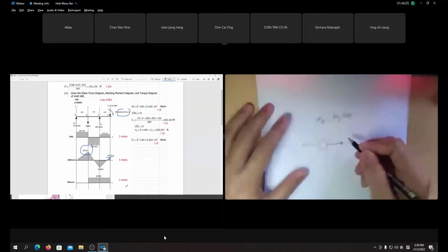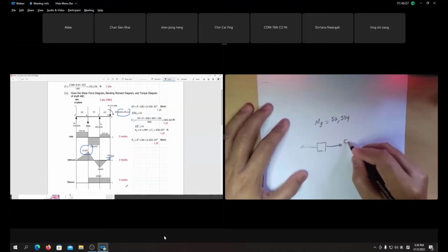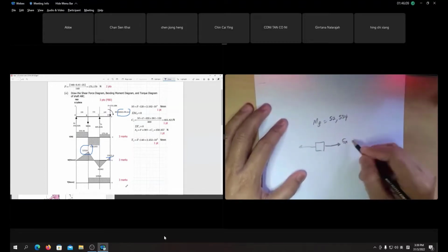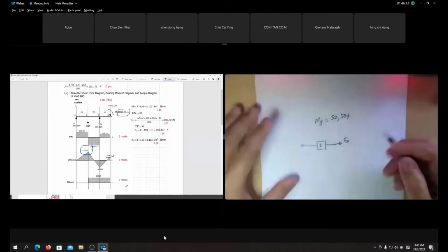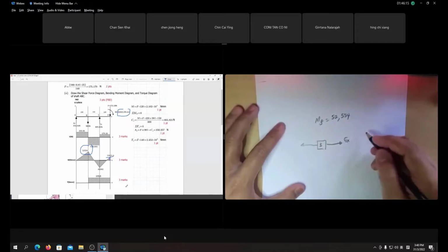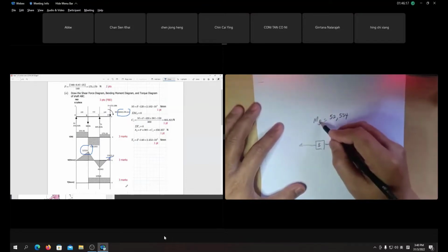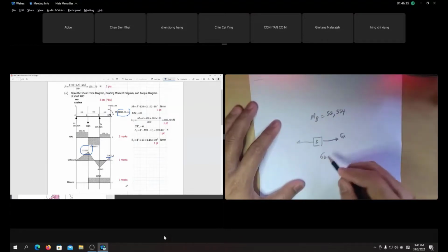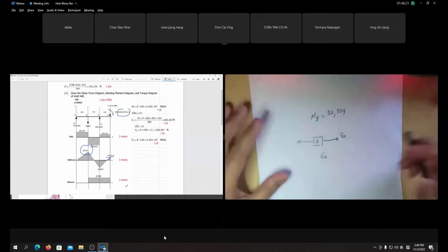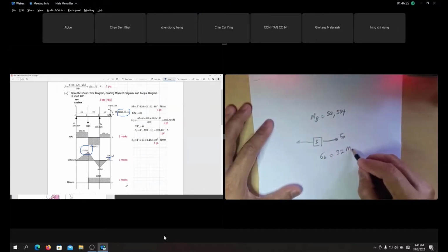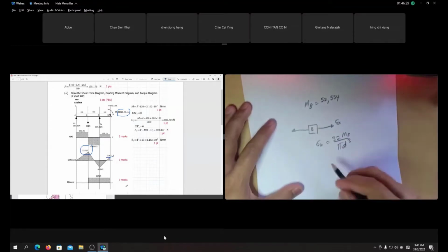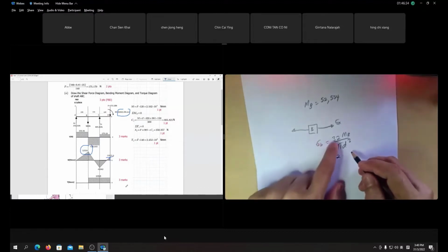Okay, let's say we consider tension. Sigma X is bending stress because of the moment at element B. What do we have for sigma X? Bending moment. We don't have any axial load, right? Only moment. What is bending stress? It is 32 times moment at B over pi d cubed, for a solid shaft. This is only the equation for bending of a solid shaft.